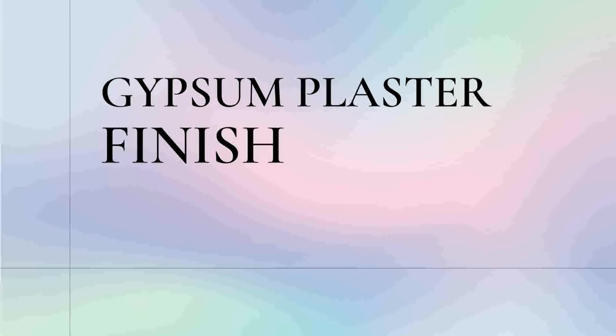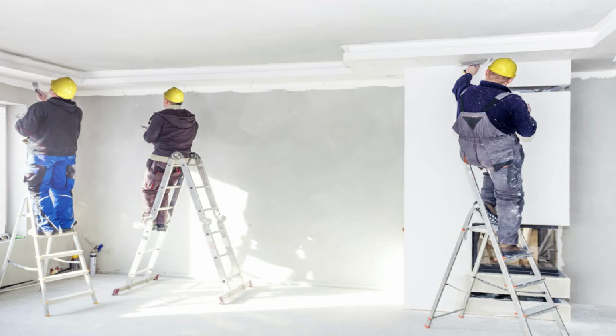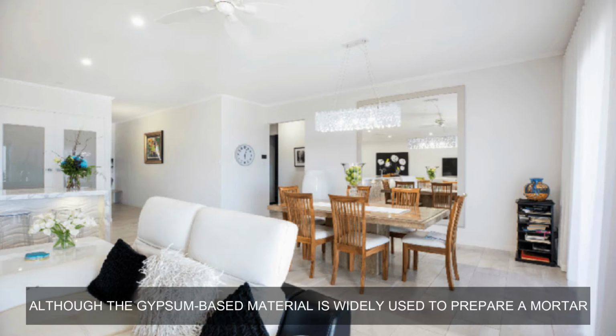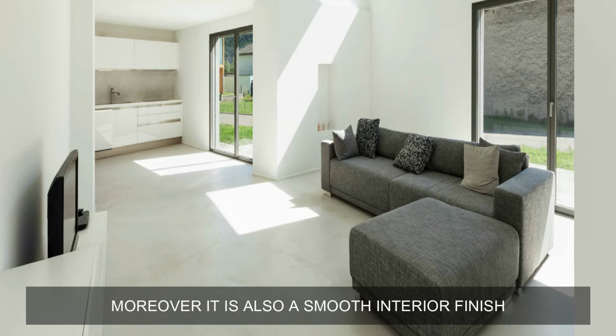Next up, we have the gypsum plaster finish. Gypsum is a soft sulfate mineral composed of calcium sulfate dihydrate. It is widely used as a fertilizer, in molds, in sculptures, and as a plaster material. Unlike cement plaster, it doesn't shrink during drying and hardening processes. It is lightweight, non-combustible, prevents rusting of metal fittings, and has low thermal conductivity while giving high tensile and flexural strength. As we know, this finish can be compared to that of the plaster of Paris finish, although the gypsum-based material is widely used to prepare a mortar. It is also more durable and more refined. Moreover, it is also a smooth interior finish and an ideal base for good quality paints and wallpaper finishes.